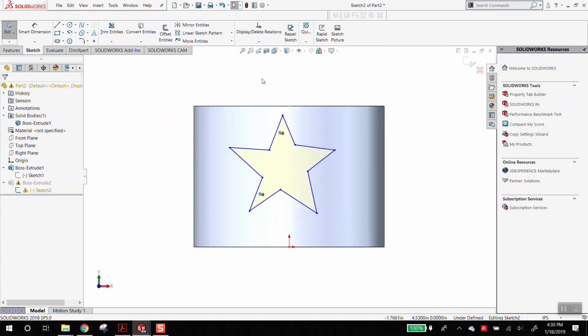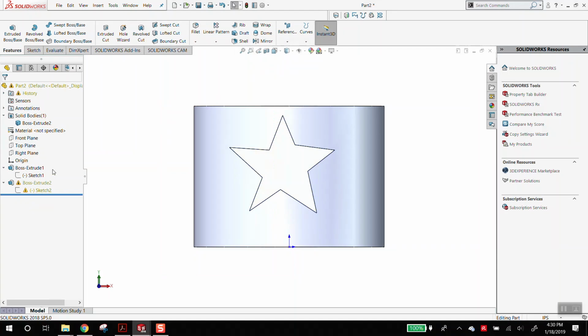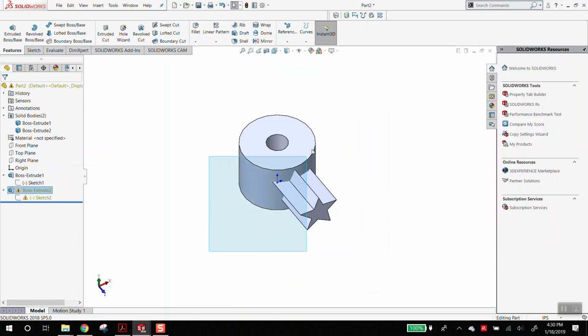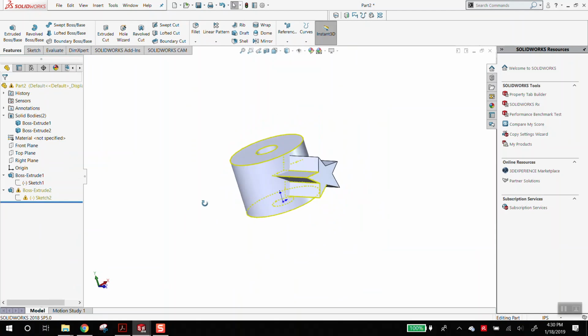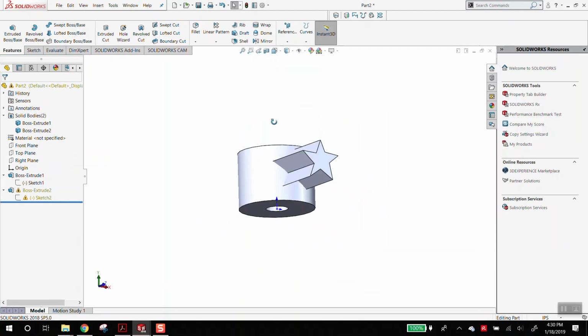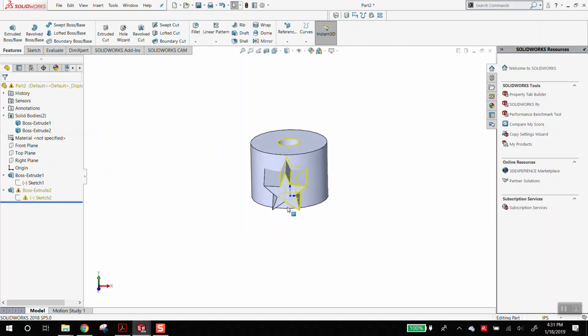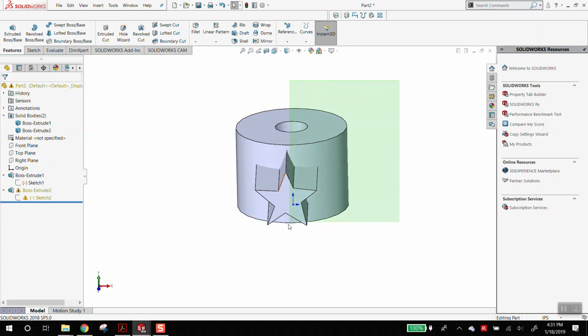So let's check your answer, let's see if we can answer your question for bodies. So let's, again, go back in here, tell it I don't want it to merge. I want them to stay separate. And let's see, bottom left up, it selected edges. Okay, so let's try that again. Bottom edge up and bisecting those. It did not select them. Bottom edge down. It seems that when you're on the body, or when you're out of a sketch, it doesn't matter. It's never going to select it unless it's fully inside.